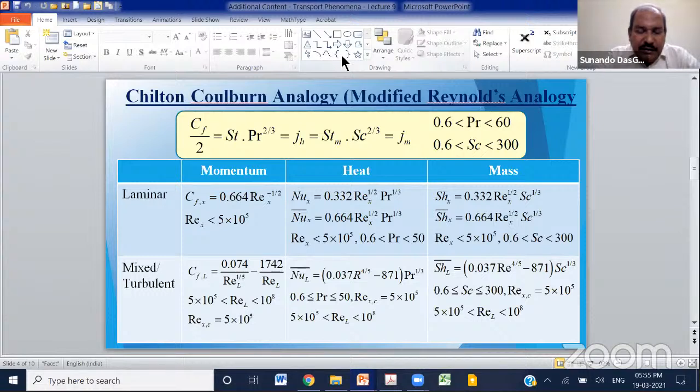First of all, in the fluidized bed, the entire situation is highly turbulent. So if you are going to find out what is the convective mass transfer coefficient, you will have to rely on experimental data, and the experimental data on heat transfer in a fluidized bed are more common. So you could extrapolate using analogy the equivalent form of the Sherwood number relationship from the Nusselt number relationship. So if the Nusselt number data is known to you, then using this relation, you would be able to obtain the convective heat transfer coefficient for such systems.